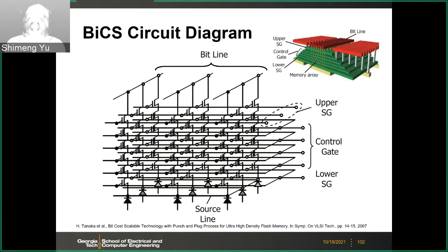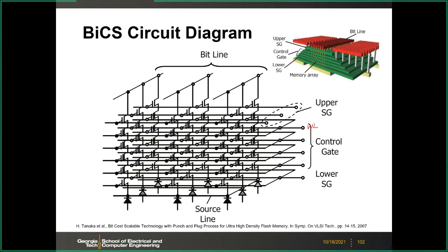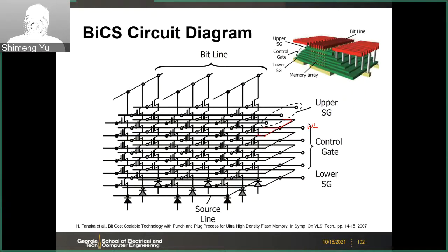One layer is one word line in this case, and this word line is shared between those strings. So here you see those three. For example, those three transistors' control gates are connected together, right? And they are shared at the end of the word line. So those are shared on the same layer. This is the word line.